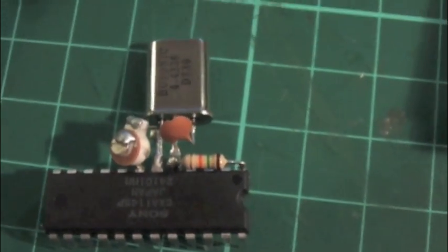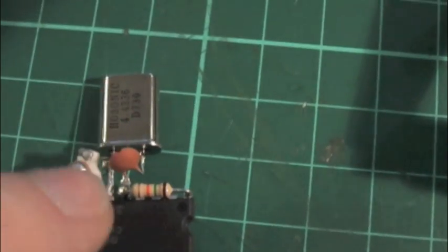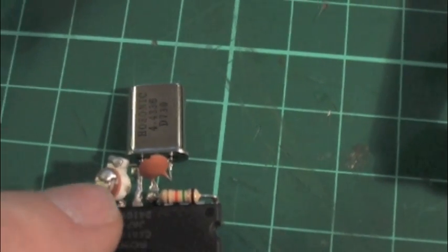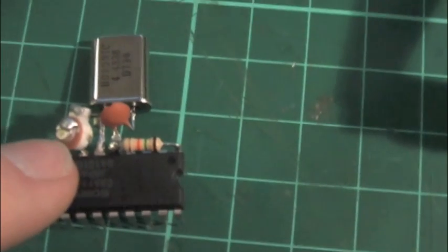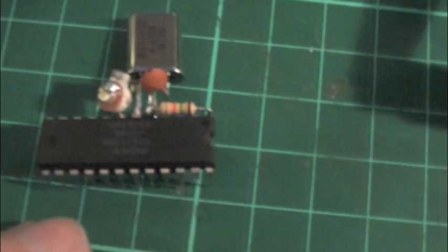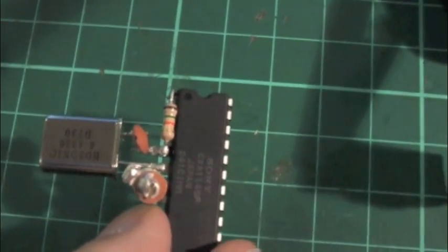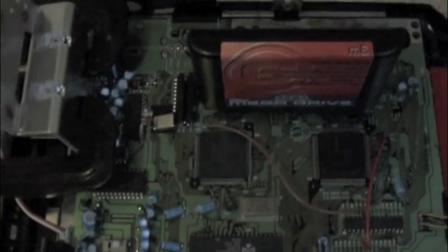Okay, so that's the chip all set up, and the crystal is now in. There's a resistor, a capacitor, and then here is a variable capacitor just for fine tuning. All I need to do now is literally drop this back into the motherboard and ground pin 1 to pin 7 on the other side, and that's that. Okay, so the chip's back in place, soldered in, and I've wired underneath 1 to 7 to make it permanently ground, and now we should have PAL 60 and 50 Hz coming from this crystal here.